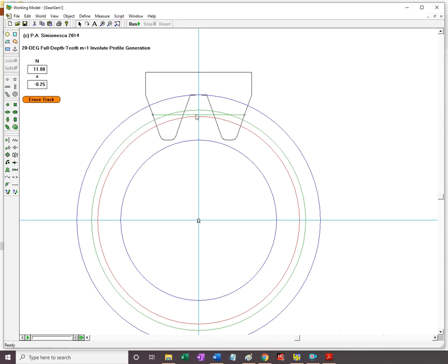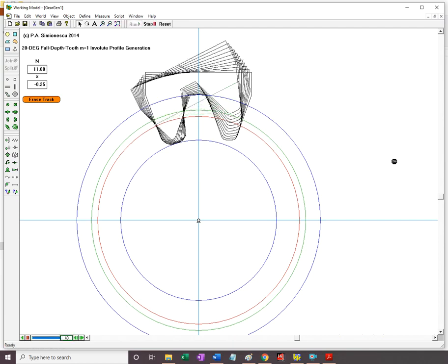So now I'll have a line that is offset towards the addendum of the cutting tool by the same amount. And now rolling without slip happens about this line, the line that is offset, not shown, tangent to this point, which is going to roll without slip the rack relative to the pitch circle of the future gear.